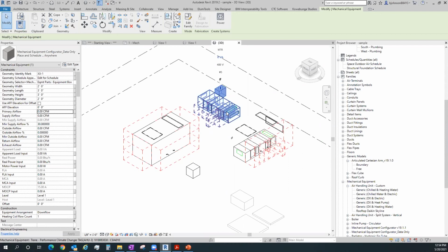Boiler, chiller, water tank, whatever it might be. Those are all pieces of mechanical equipment by Revit category, and they need to be separated on schedules, so you don't have one master schedule with every bit of mechanical equipment in it. So having a parameter like that, you can say, I want to schedule this thing in my schedule and keep everything else in mechanical equipment world completely away from it.